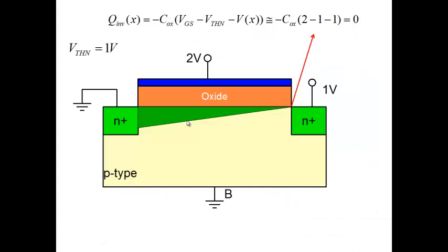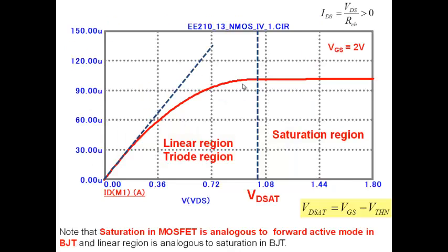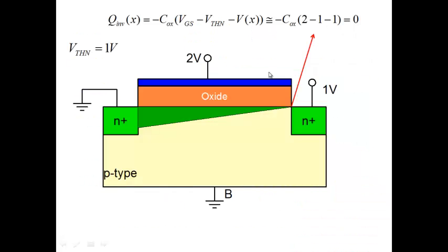All right. Now let's see why saturation is a complicated phenomenon. Let's try and understand. We know that current keeps on increasing, but it doesn't increase as rapidly because R channel is also increasing. As I increase my drain to source voltage, R channel is also increasing, and eventually we are saying that the current saturates. Now let's see what happens here.